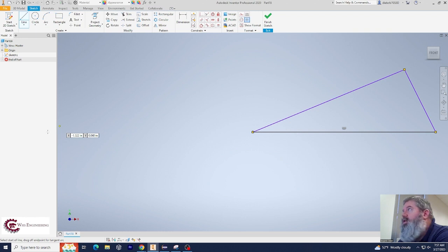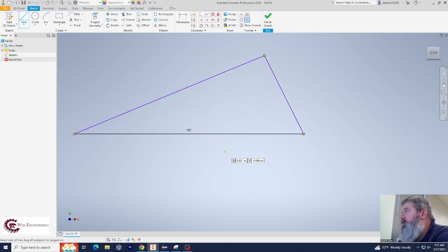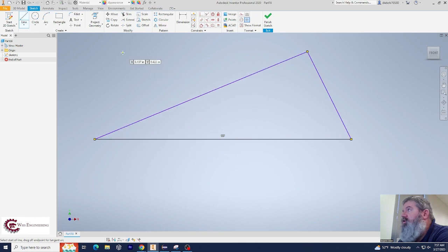If we want to display the existing constraints, which is the first thing I want to do to see what I drew, you can already see one right there. That's an existing constraint. You go up here to this button, which says show constraints. Then you pick which line you want the constraints on. You notice the only line that has a constraint on it right now is this horizontal line. None of the other ones do. So you see the horizontal constraint, and like I said, there's not any on any of the other ones.